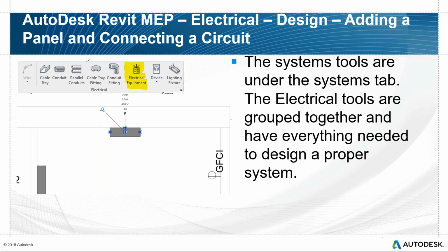You can just add them like you would any other Revit component. So you would add those panels to the walls, and once you add the panels, you place it where you want it to go. You can start checking to make sure that it is not going to be under a pipe, or you can start looking at those clash areas now, to make sure your electrical panels are going to be placed properly.